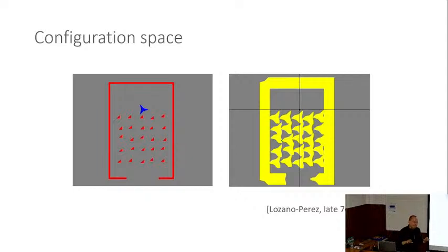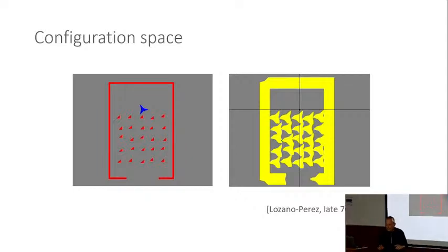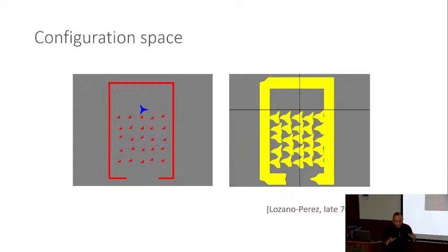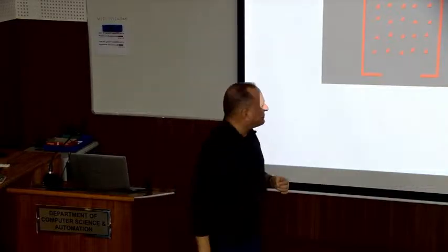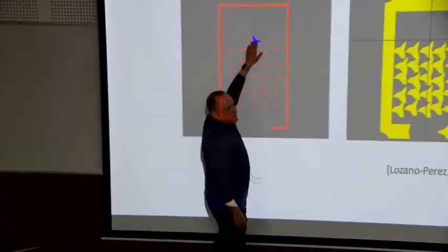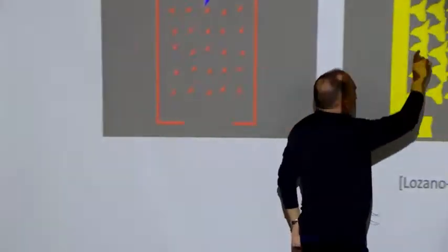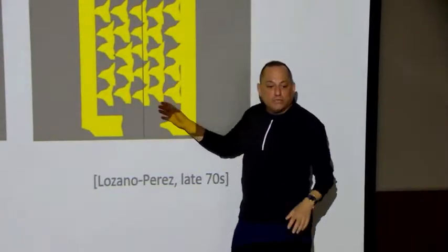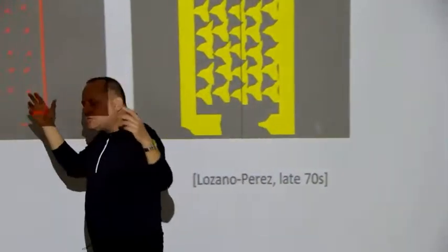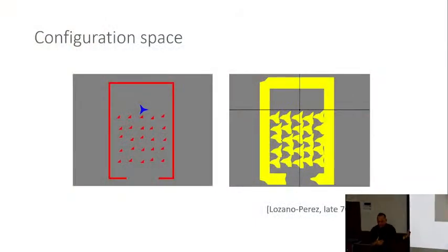Configuration space is a very nice idea that unifies many motion planning problems. You take your robot system and actually you shrink it to a point. And you study the motion of this point in a space whose dimension is the number of degrees of freedom. Because every point describes the full static position of the system. Here you see an example for a robot with 2 degrees of freedom, only translating parallel to itself. So it's equivalent to planning the motion for this point among these expanded obstacles.